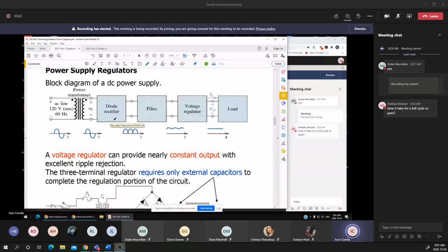After the voltage is converted, the AC voltage on the secondary of the transformer is now converted into an output voltage, which is the rectified voltage. The rectified voltage is now filtered using a capacitor, and you may see a voltage regulator. Now, next week,